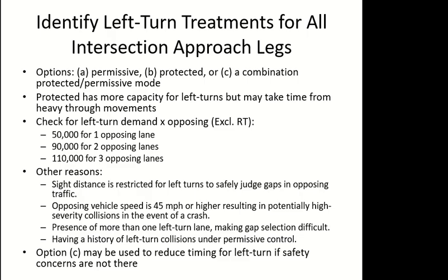First thing, I told you the first step is to find out if you want to make the left turning permitted, protected, or a combination. I told you combination is confusing, permissive can also be confusing, and it can be dangerous as well. So basically what we are saying is, do we need a separate phase for left turning, or do we keep it with the straight? This is the question we are trying to answer.